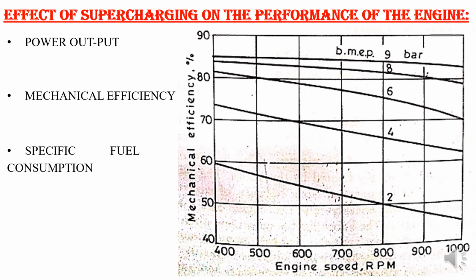So we can say that in spite of better mixing, better combustion, and reduction in delay period, a mechanical supercharged auto engine will almost have a specific fuel consumption higher than that of a naturally aspirated engine. Understood? Because in part load, whatever extra power is generated is given only to drive the compressor, so there is no output increase, but fuel consumption stays at the same level.